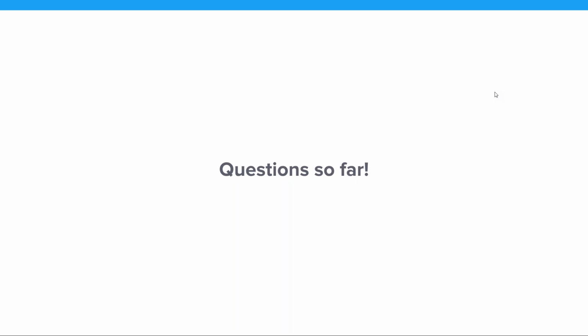Okay. Sounds like a good answer to me. Where can we find information about various material deformation during molding so we can make a pre-estimation for scaling for the mold? I'd look up the safety data sheets and the technical data sheets for whatever material you're using. Dave, is there a particular value that people would be looking for? For deformation, or what? I'm assuming when the part shrinks, they're looking for that shrinkage rate. Is that what it's called?